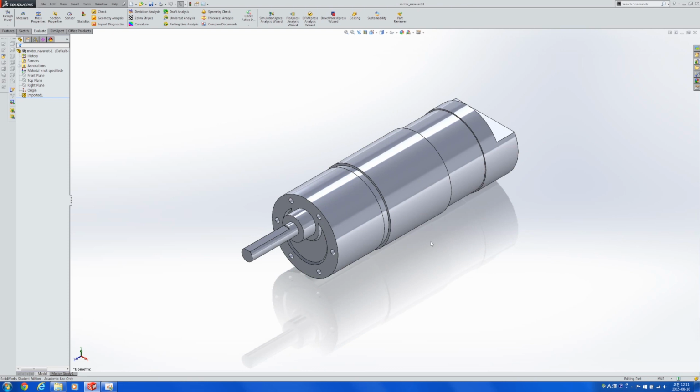From now on, I might be talking a little bit more about CNC milling, which is basically a computer-controlled drill that goes through a solid plate of, say, aluminum or plastic or anything, so that it makes a desired shape that you design in SolidWorks. Usually the cheapest parts that you can design are 2.5 dimensional parts, which means that once you get a drill and you move it around, as long as you have the plate that is of the right thickness, you will get the part that you want. So there are no difficult features to design.